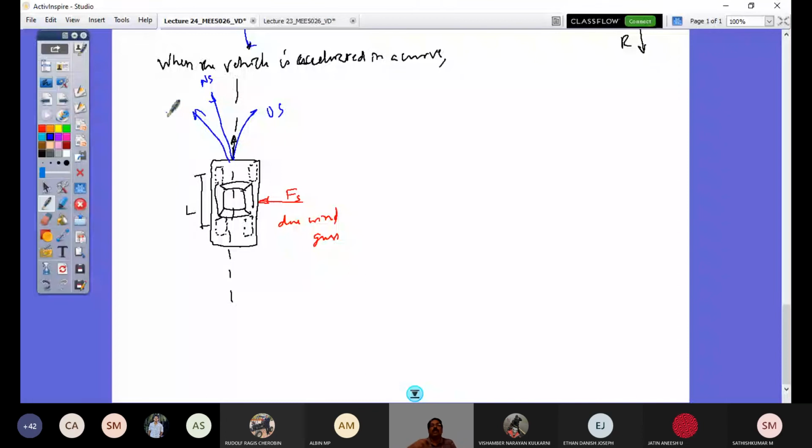So your correction would be to the side where the force is acting for an understeer vehicle as well as a neutral steer vehicle, to keep it in a straight direction. Whereas for an oversteer vehicle, if you get the wind from your right side, you have to steer to the left direction. So that is the meaning of the understeer, oversteer, and neutral steer effects here.